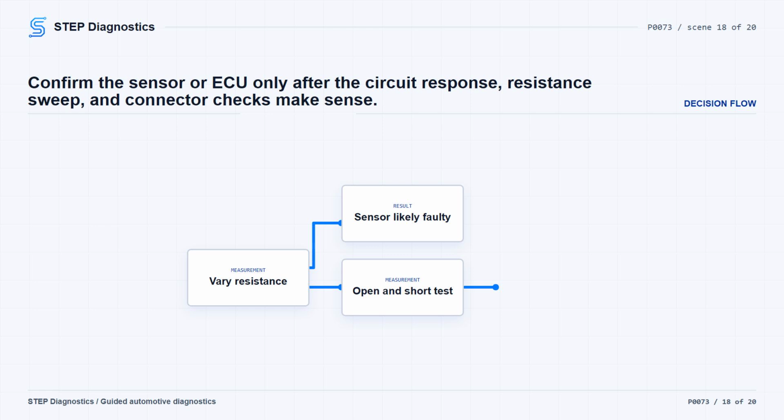If a temperature table is not available for the sensor being tested, connect the electrical test kit leads to the harness connector. Flip the switch to adjust, turn the ignition on, and slowly adjust resistance while watching scan data. The temperature or voltage value should change as resistance changes. To verify an ECU failure, open and short the circuits while monitoring signal voltage and fault codes. If the expected voltage readings or fault codes do not occur and the circuits are not shorted or open, that points to a faulty ECU.